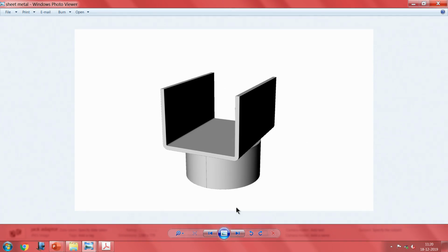So, I will take a break of this whole session here at this point, so that you will try to see how well variations and production also have to be incorporated into your designs. While solid modeling is convenient, I can make a very impressive looking thing. One way of dealing with it is probably to make two of these parts, one at the extreme upper end of the tolerance, another at the lower end of the tolerance, and see whether they will fit each other by manually trying to show them on your screen. That will only clarify your concepts for you.